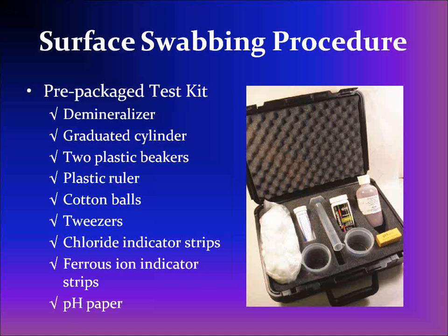The prepackaged kit contains all of the necessary equipment needed to collect a sample from the surface, then test the sample for chloride, ferrous ion, and pH. There are a few calculations that have to be performed once the extraction is complete.